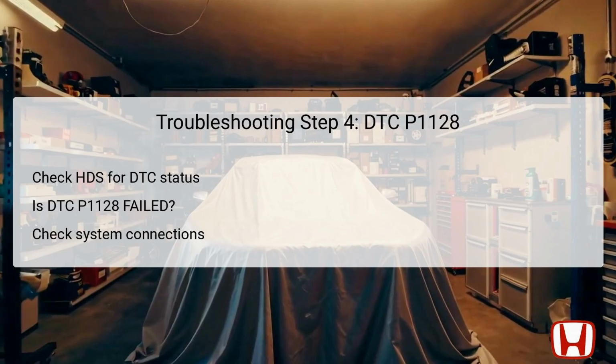After completing the test drive, monitor the onboard diagnostics OBD status through the HDS to check if DTC P1128 is indicated as failed. If it has failed, it signifies that the problem persists, which requires you to check for poor connections or loose terminals specifically related to the MAP sensor and the engine control module ECM or powertrain control module PCM.